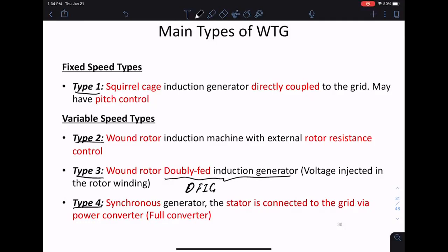And then the new one is called the synchronous generator. This is basically replacing an induction machine with a synchronous machine, and you get rid of the need to have a synchronous speed. We don't need a synchronous speed anymore. This is a full solid-state, converter design.